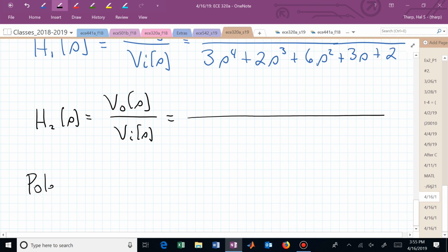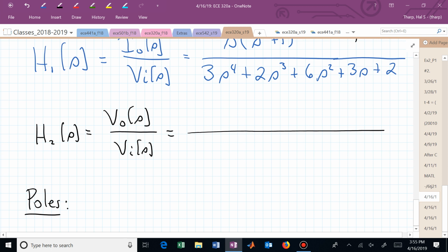Where are the poles? I'm guessing somebody's already factored that. That's kind of a mess. Is that polynomial monic? And have I defined monic before? Is the denominator polynomial monic? What do I mean by monic? If a polynomial is monic, that means that the highest power of s has a coefficient of 1. We've normalized the coefficient of the highest power of s to be 1. Here we would have to factor that 3 out and put it upstairs, so you could have a 1/3 in the numerator. We didn't do this, so that denominator polynomial is not monic.